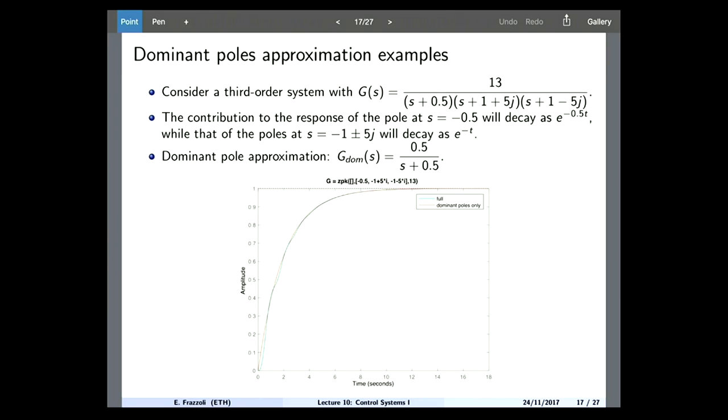Okay, so the one thing that you had to do is you just cannot get rid of one of the factors, okay? What you had to make sure is that the DC, the Bode gain, is the same. So just remove whatever needs to be removed and just make sure that the Bode gain is the same, okay?